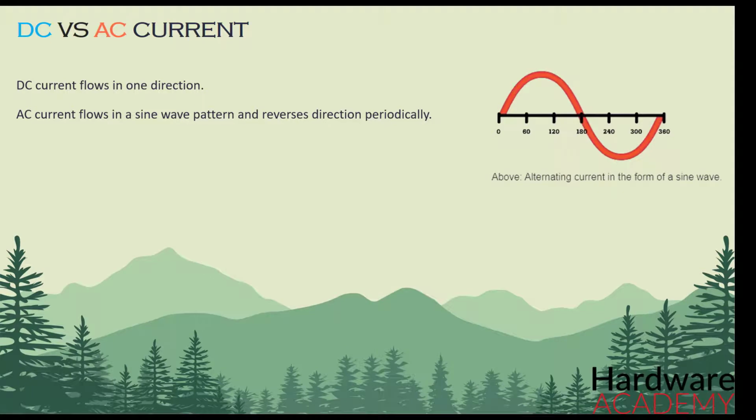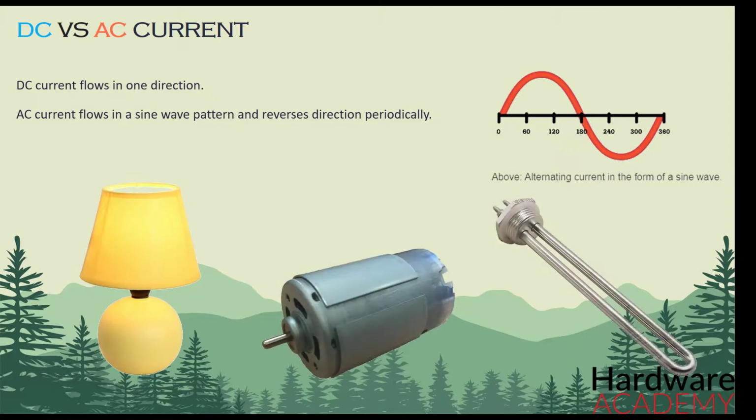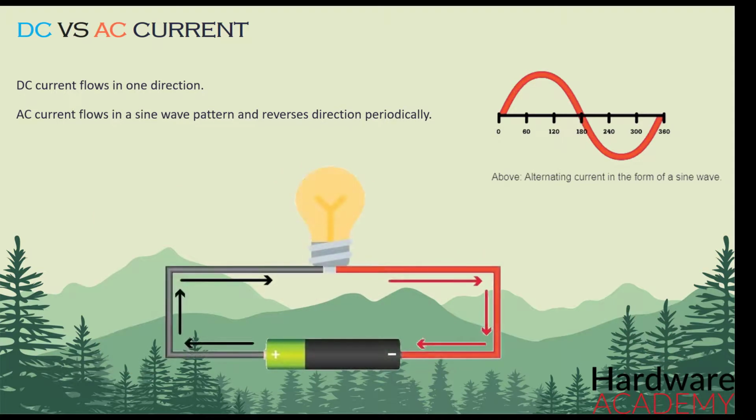You might already know this and it's kinda evident, but any component like a lamp, motor, or heating element that converts electrical energy into some other form of energy like light, rotation, motion, or heat uses current. As we said in the previous course, this light bulb in engineering terms is called a load. When additional loads are added to a circuit, the circuit must deliver more current. And the size of conductors, fuses, and the components themselves will determine how much current will flow through the circuit.